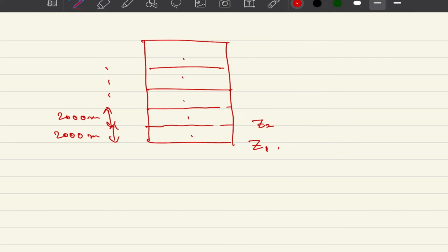So I should write P1, temperature, and hence E1 at these levels. So Z2, P2, T2, and E2, all these things would be measured at these levels, which can give us the magnitude of specific humidity, which we can plug in the formula and get our answer as an average for these columns and add up all the values to get the total precipitable volume of water that is present in the atmosphere.